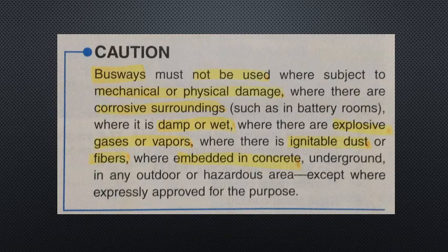Caution: busways must not be used where subject to mechanical or physical damage, where there are corrosive surroundings, such as in battery rooms, where it is damp or wet, where there are explosive gases or vapors, where there is ignitable dust or fibers, where embedded in concrete, underground, in any outdoor or hazardous area, except where expressly approved for the purpose.